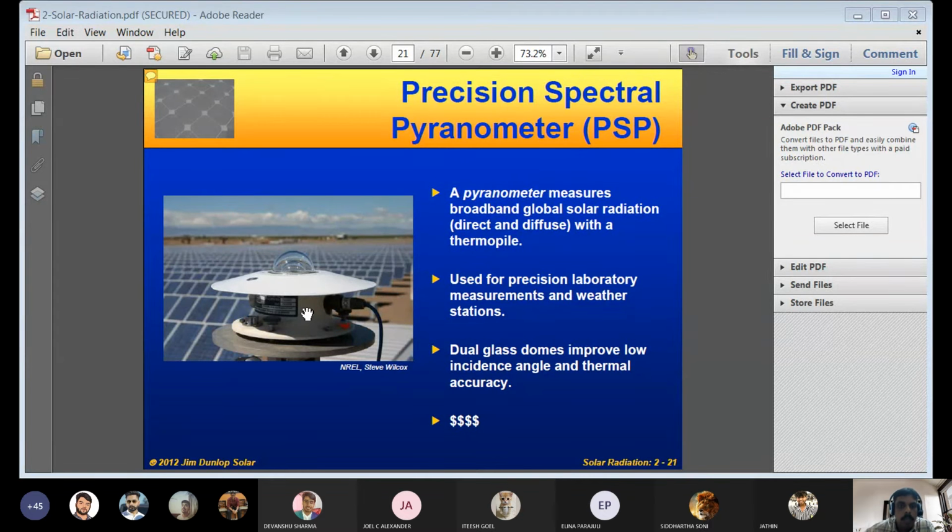So here we can apply the same thing. The sensing element will be there under this glass cover. We make solar radiation impinge on it, so that sensing area will get heated up, right? The other junction we keep inside the body, which does not receive solar radiation, so it stays at ambient or normal temperature.